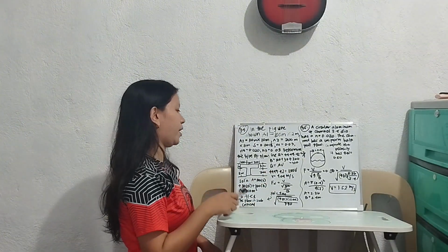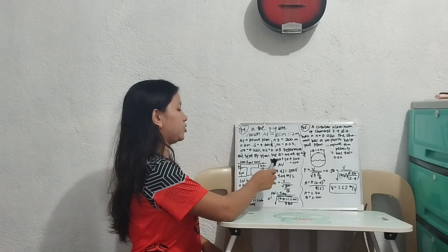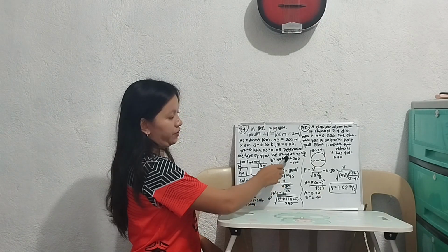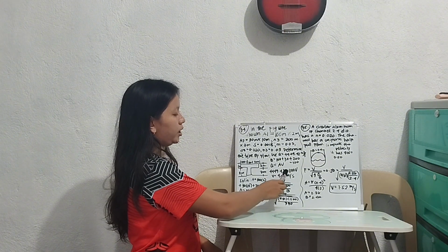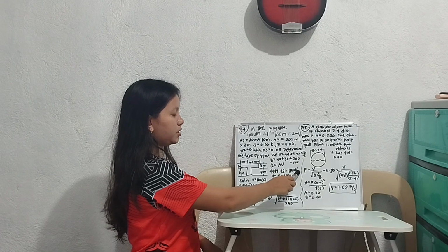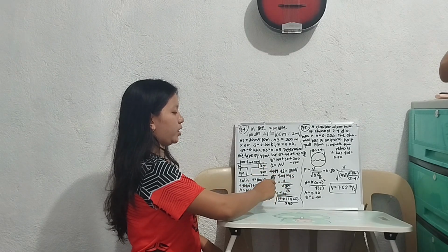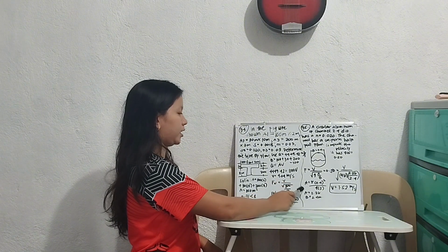Next, we need to find the velocity. So we have the formula Q is equal to AV, where we have the Q given, 4,449.42, equals the area of 1,100 times velocity. So to calculate that, we came up with the answer 4.04 meters per second.